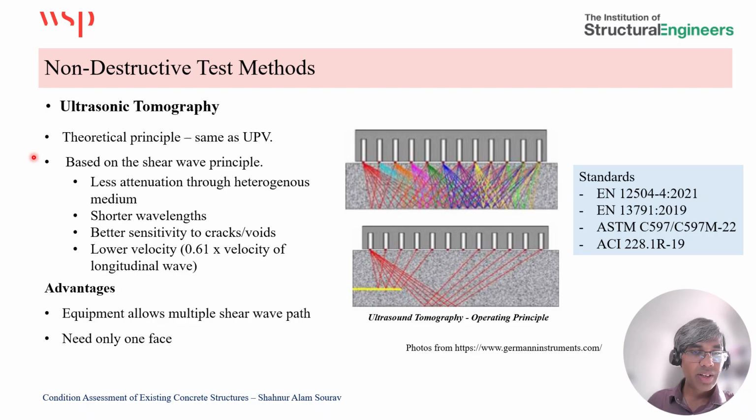Ultrasonic tomography: the theoretical principle behind this is similar to ultrasonic pulse velocity that we have already discussed. However, there's a difference in the type of waves that this particular equipment uses. This equipment is based on the shear wave principle.